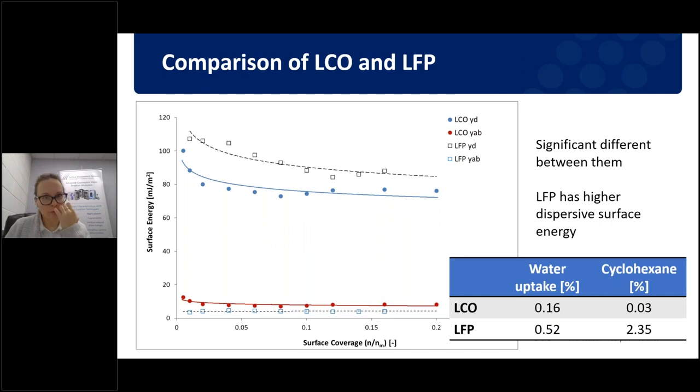We also measured recently the lithium iron phosphate surface energy at 100 degrees C, and we compared it with the LCO. You can see that there's a significant difference between LCO and LFP. As Johanna also mentioned, LFP has a very, very small specific surface energy, even smaller than LCO, and it also has a higher dispersive surface energy.